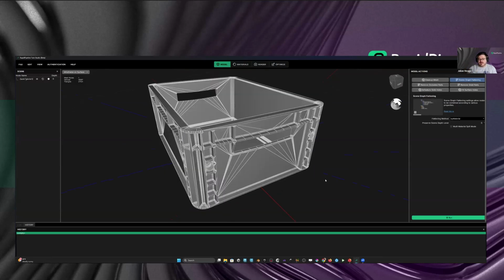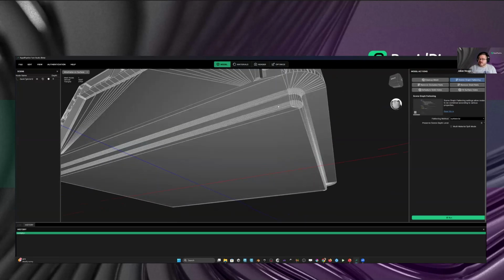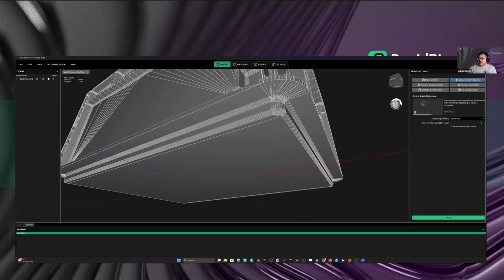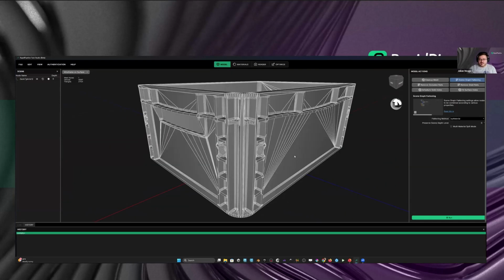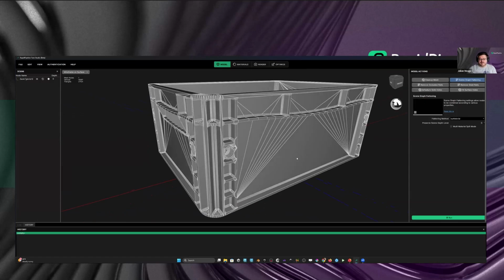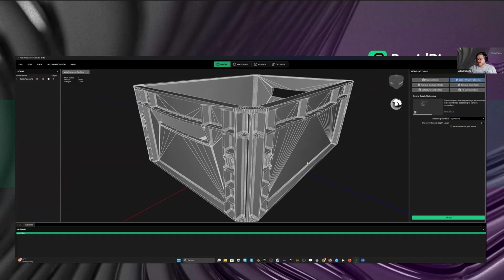If you ask why quads for CAD files, I don't want to do a squishy Pixar style animation on it. So why would I even need that in the first place? What we found, and that was a lot of customer feedback as well, is that it might help later on if you're doing certain manual operations on a file, that you're easier able to select edge loops, and you can basically identify certain problems with the model quicker if you do a manual roundup. So I think that's the main point, and happy to hear your opinions and questions on this. But that's the gist of what we got from the user feedback: on a hard surface asset, actually maybe not needed, but it's really cool to have them just to be able to work in a more simple way.